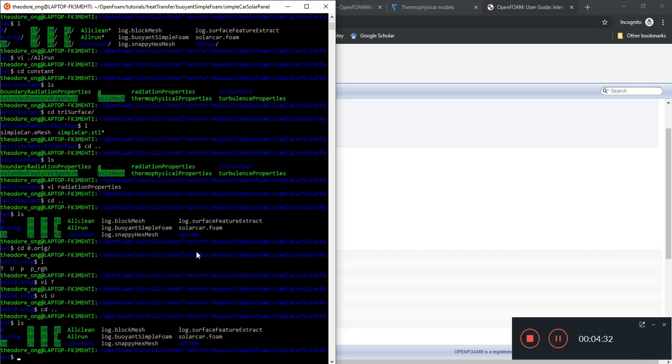So at least from this tutorial we can see that you can use snappyHexMesh with buoyantSimpleFoam. It's not too big of a deal, and we have demonstrated how to do snappyHexMesh properly in the intermediate tutorials. So we can try something perhaps in future videos when we look at more complicated solvers, because buoyantSimpleFoam is a really simple case. It's a steady state kind of calculator.